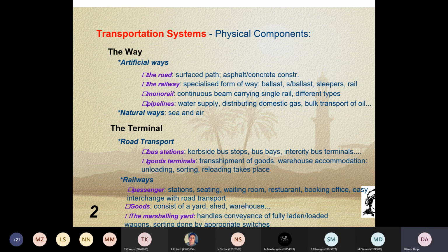When it comes to the ballastless system, that is equivalent to your rigid pavement. So with the ballastless system, you have a concrete slab that's laid, and immediately above your concrete slab, you have your rails fixed. You don't have these superimposed layers that I was referring to, your sub-ballast and your ballast, these single-sized stones that I was referring to. So you can see there's a correlation between road and rail in terms of the construction.